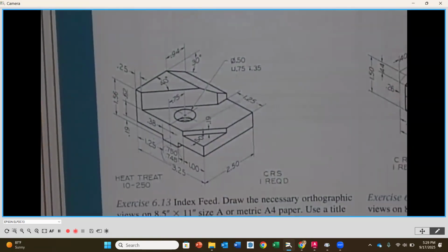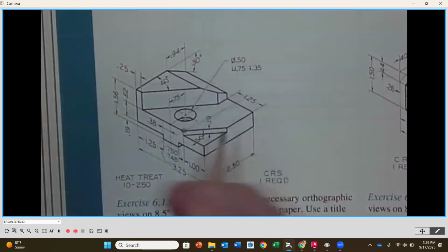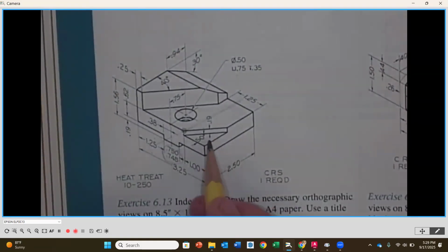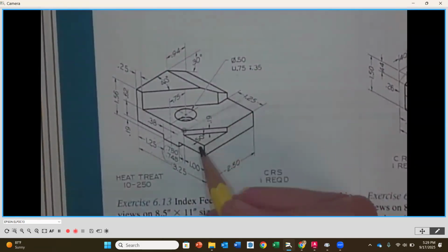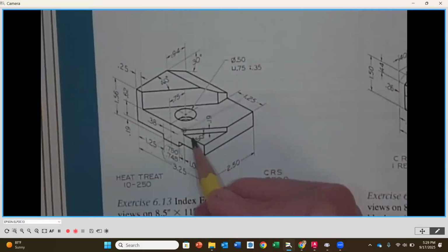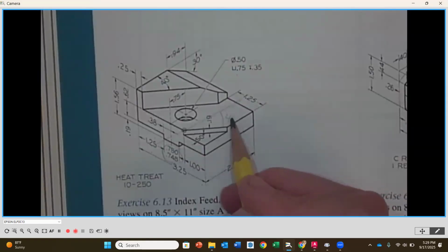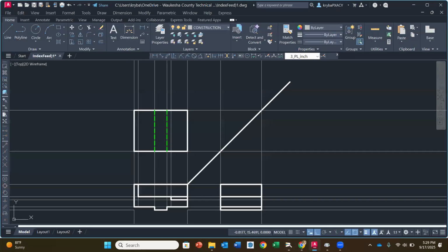Okay. What we're going to do is we're going to grab this base point where it intersects with the front of that top view, and we're going to rotate it so that it's going to be 50 degrees from horizontal. But because this is, if you would, vertical, and if we go from here down to here, that's 90 degrees. So we're actually going to rotate it 40 degrees clockwise. Okay, and I'll show you this over here. It might make more sense when you see it.